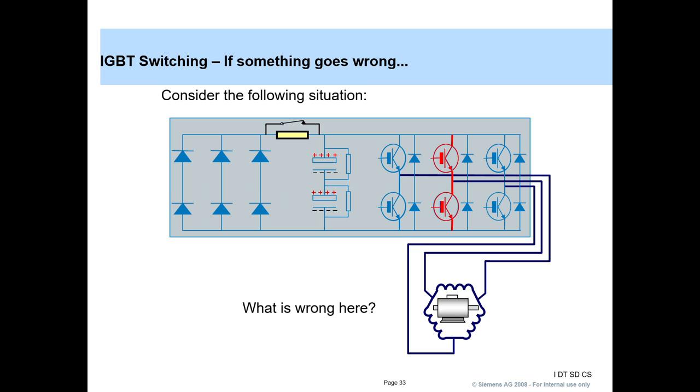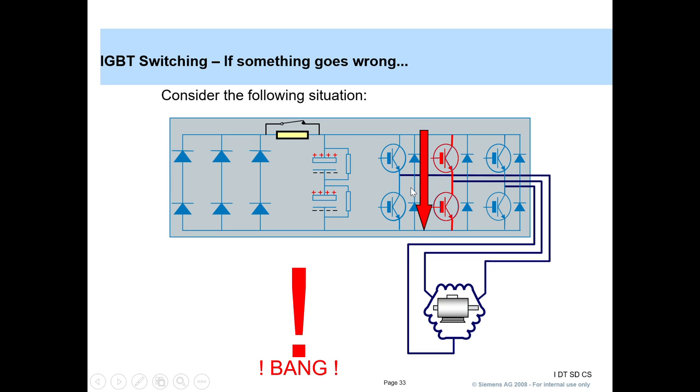So just to show how important the switching sequence is, let's consider a case where these two IGBTs are fired up by mistake. What will happen? It's a short. So this is how critical the switching is.